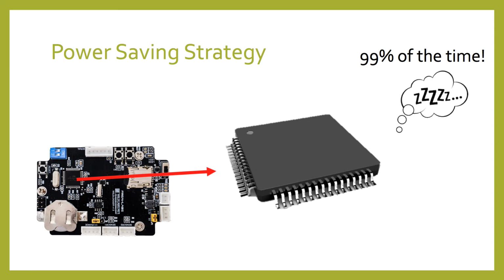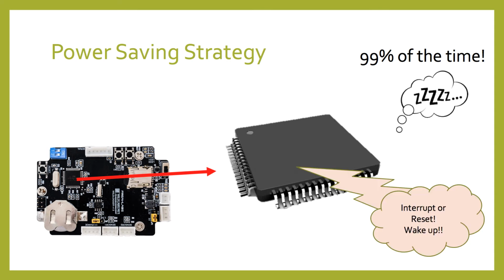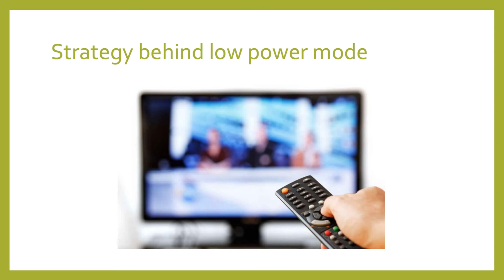And one problem with polling is that you can't do it whilst the microcontroller is in low power mode. In fact, there are only two ways for the microcontroller to come out of sleep or low power mode, either through a reset or, you guessed it, an interrupt event. This strategy to sleep and wake up via an interrupt is central to many devices.